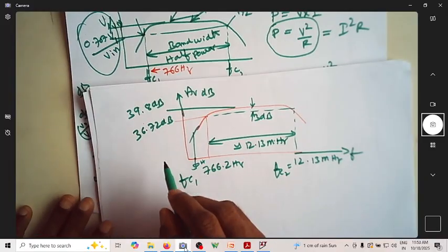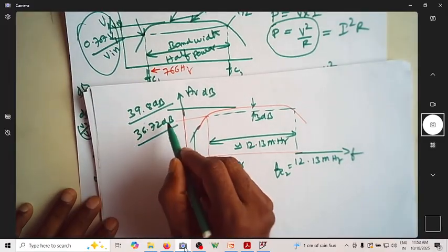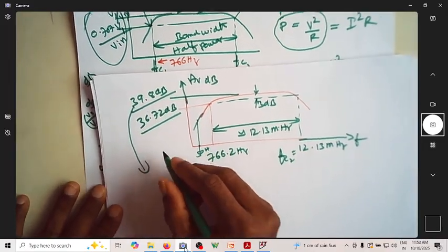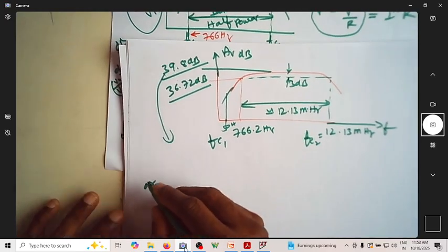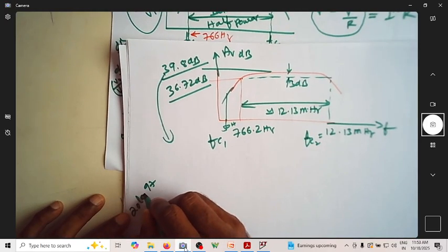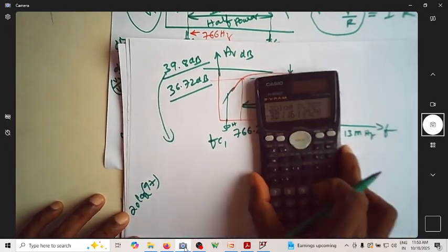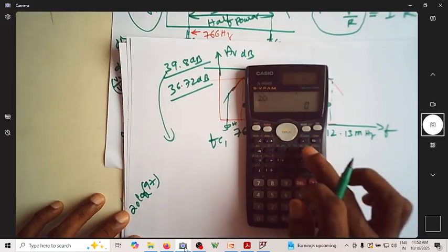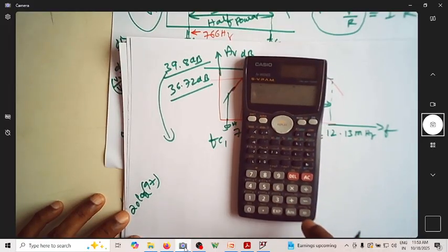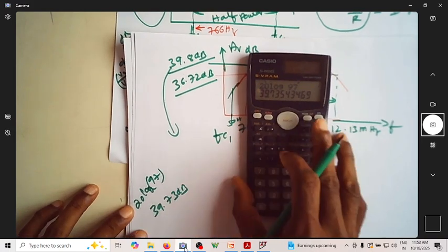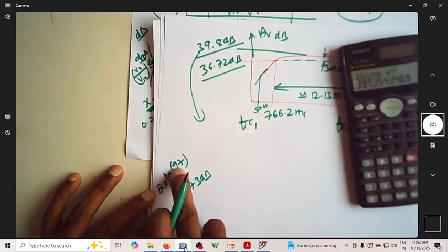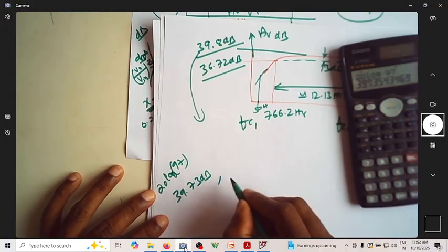So now this is in dBs. Can you actually find what the gain is? You know that if you have a gain of 97, you can find this in dB. It is 20 log of 97. So what is 20 log of 97? 20 log of 97 is 39.73 dB. 39.73 dB is 97.